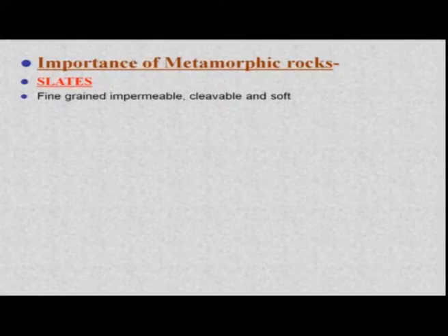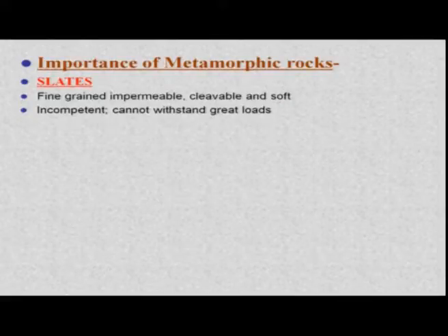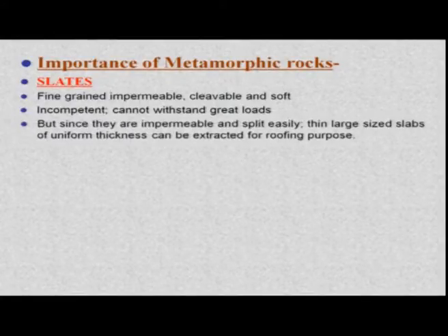Okay, so they are fine grained, impermeable, cleavable, and soft in nature. Okay, incompetent, cannot withstand great load. Okay, so if you come across slates, you should avoid putting any heavy structure on that. Okay, but since they are impermeable and split easily, they give thin, large size slabs of uniform thickness. Okay, this is because of its typical platy nature or the cleavable planes you are having.